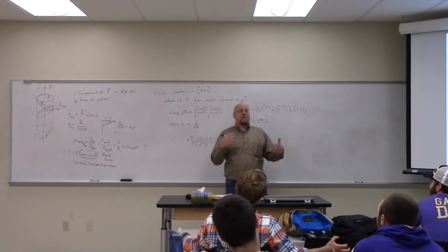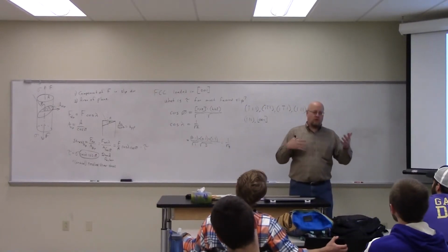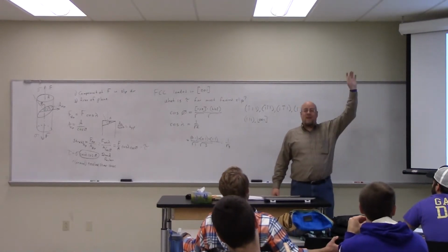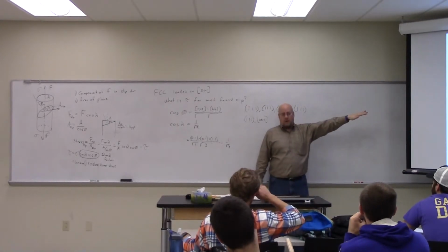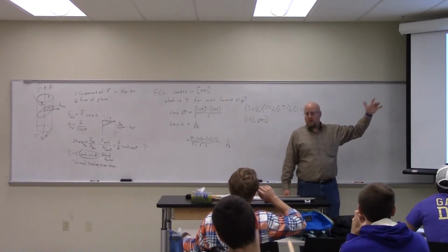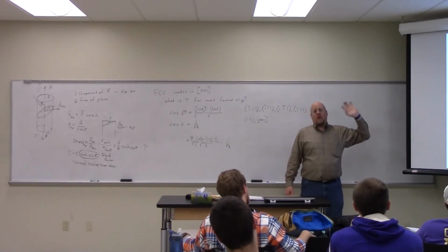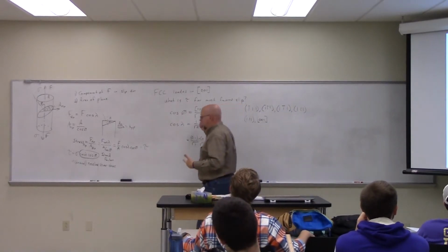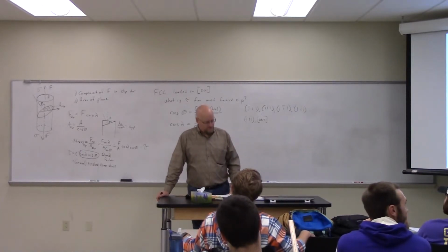Anyway, okay, so you have to try all 12, potentially. And then look for symmetry, hopefully. Like in this case, if I said I'm pulling in the 1, 1, 1 direction, I know all my cosine lambdas are going to be 0, so I'm never going to look at that plane. And then you could say the green and the yellow are actually going to be the same thing. They're kind of symmetrical about the 1, 1, 1 direction. So I'm only going to do one of those, and then I'll do the red, and we'll see what happens. So you may have to do as many as 12 different evaluations.